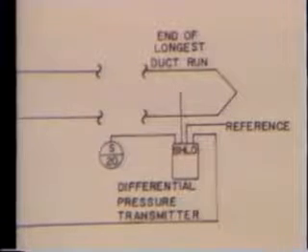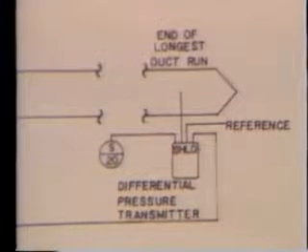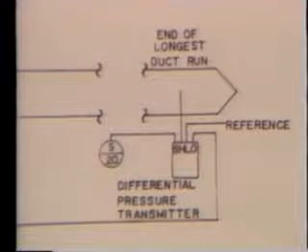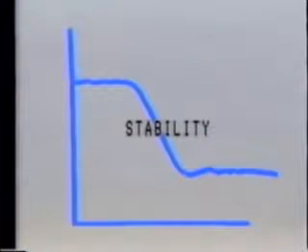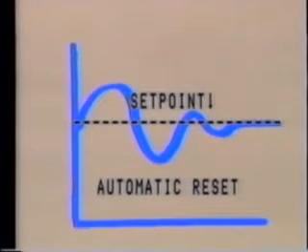Since control of the supply fan does not directly affect building pressure, stability of control is really the only major criteria for controller selection. Unfortunately, stability often dictates low controller gains, resulting in wide throttling ranges. The wide throttling range is often objectionable. In this case, controllers with automatic reset should then be applied. This type of control will automatically reset back to set point.